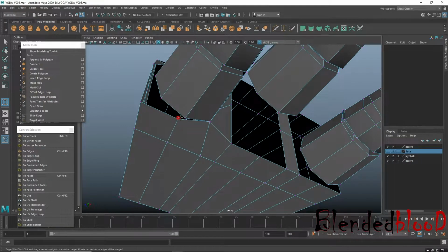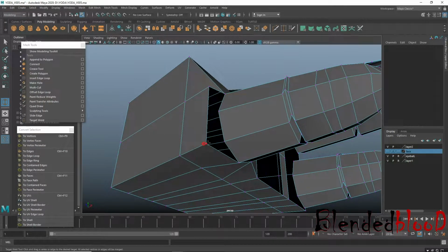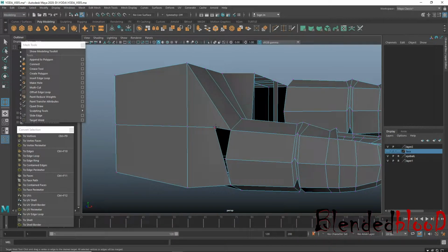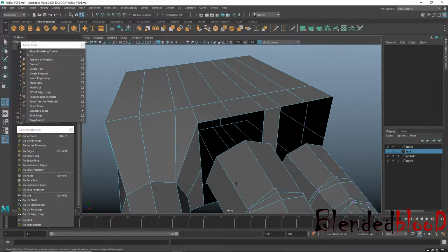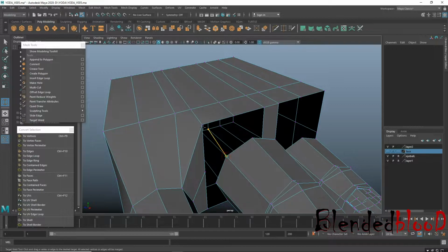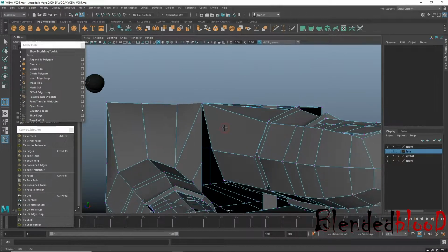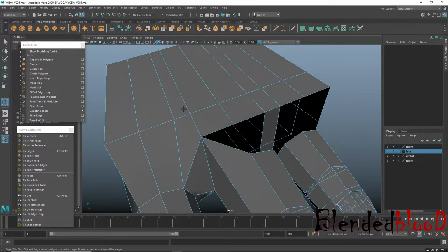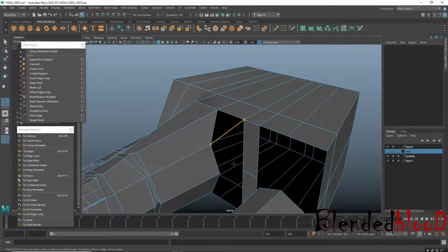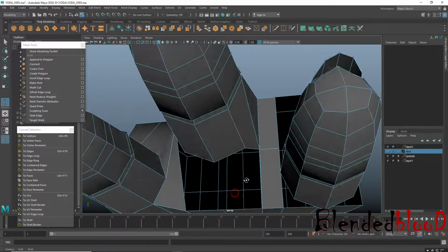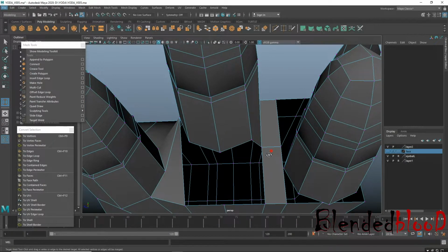And we are adding vertex on a counting basis, like our finger which we made from a cylinder. Okay, we do 8 subdiv axis and we are using 8 edge loops also in this palm area, so hopefully this will join every vertex, nothing will be left, I guess.